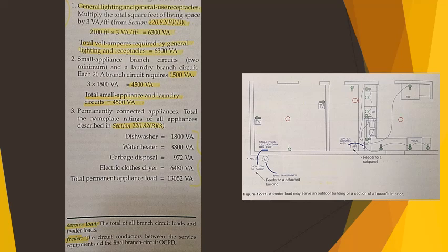This easier method may be used if the residence is serviced by 120/240 volts or 208Y/120 volt set of 3-wire service or feeder conductors with an ampacity of 100 or more. Since this situation covers many new home installations, the optional method is frequently used.